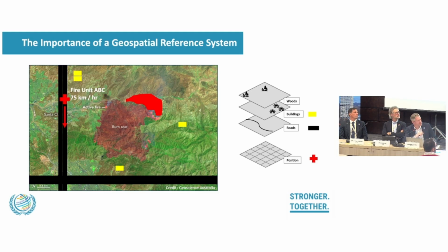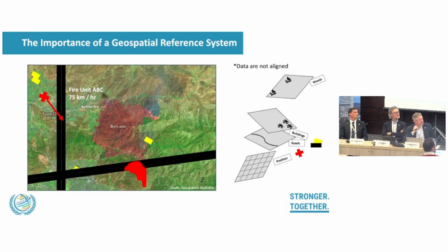But what if you're in a situation like this, where you have your houses, your cadastral layer, stored in one datum, and you have real-time GPS information that's not actually lined up with the road networks here. And then you have Earth observation imagery, which is coming from satellites, and that's sitting in a different datum. You can't actually do the decision-making you need in real time to try and help people or direct people who are dealing with an emergency. So these kind of examples can be used.